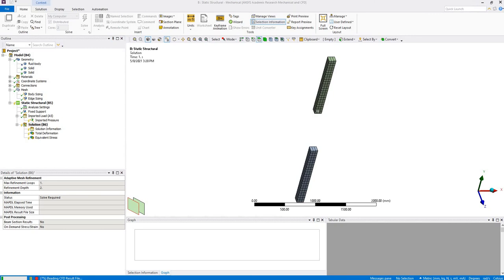As you can see, it's 7%, and what I noticed is it immediately jumps from 7% to almost 100%. So you just have to be patient and let it finish. Don't think it crashed or anything, just wait for a while and it will be done. After that we'll see the total deformation and the stress acting on these surfaces from the fluid flow.